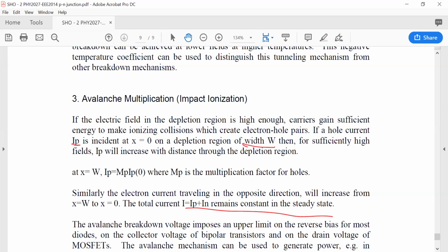So it's very important to realise that there is a sort of limitation to the operation. We don't need to go into more detail of the breakdown mechanisms, but we need to be aware that there's a maximum voltage possible before the junction and the device will break down. It's also worth remembering that the different diode types have different breakdown mechanisms and characteristics, and so you usually get an increase in the reverse current with increasing temperature, and good heat sinks are therefore going to be necessary to cool the device. But as long as you're aware of which material you've got and what its operating limitations are, you can usually account for these and get a good operation of the device within the limits available.